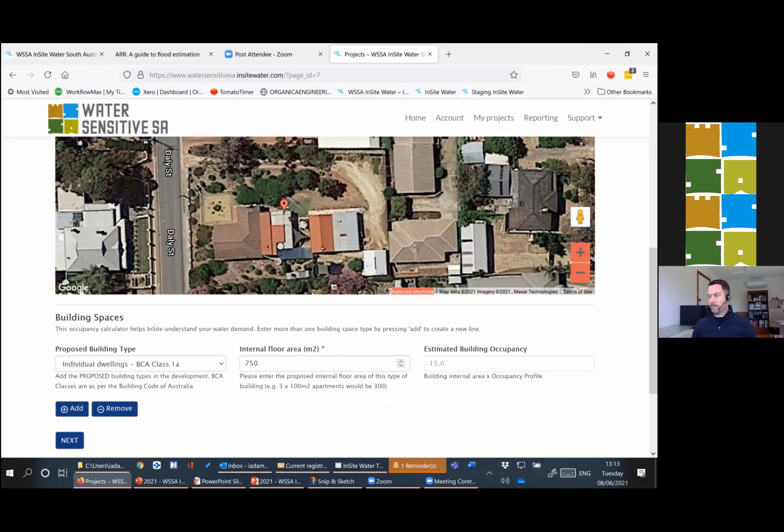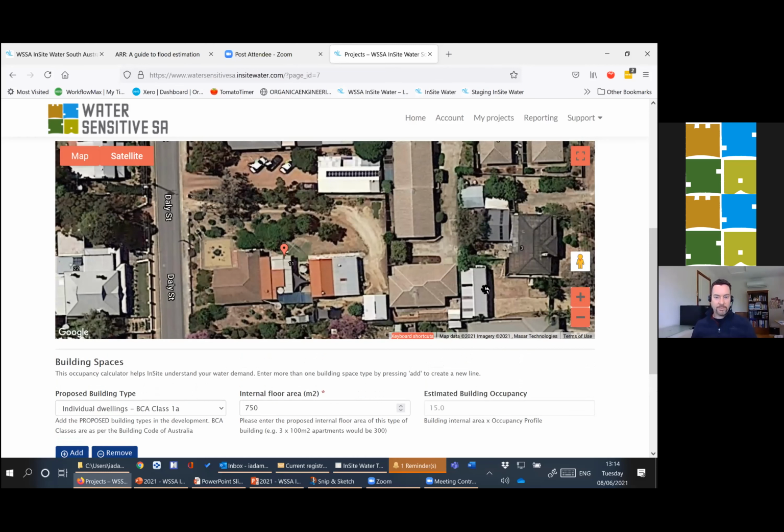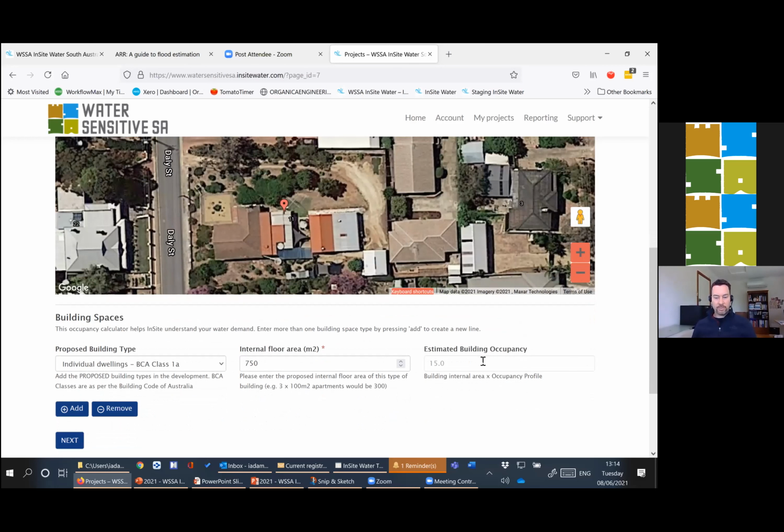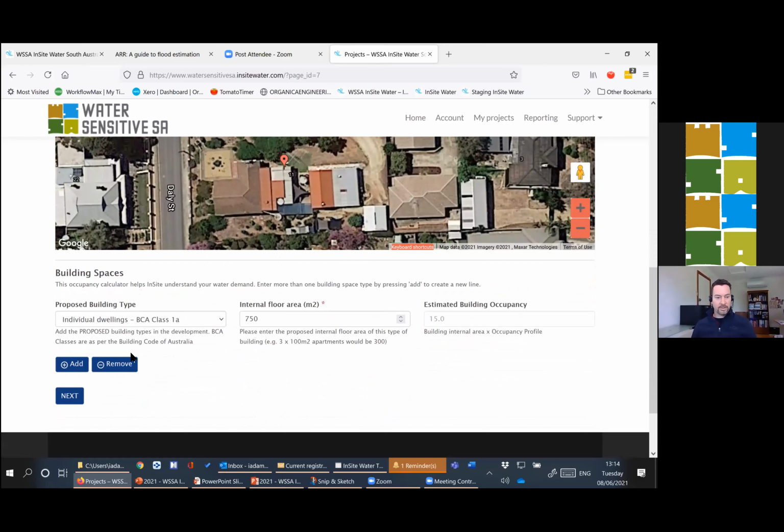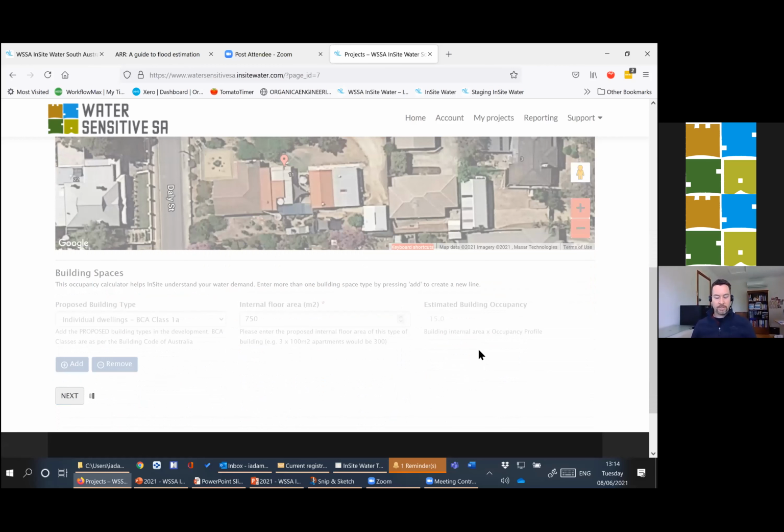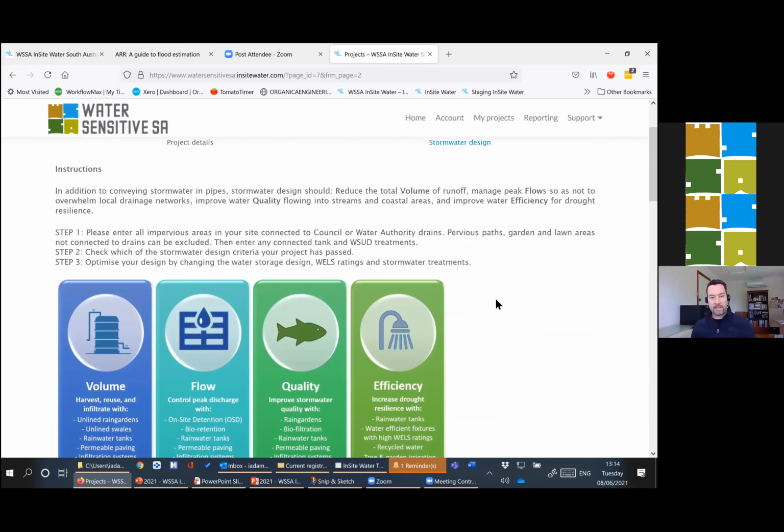All right, sorry, I should be looking at, yeah, so we have a question about maintenance. I'll come back to that, some of these systems as well. And Melissa's answered that. So we need to work out basic building occupancy because that lets us work out our water balance for our site. The number of people in the building will determine the demand and the drawdown on the tanks. So this is a really simple calculator to try and just estimate average occupancy.